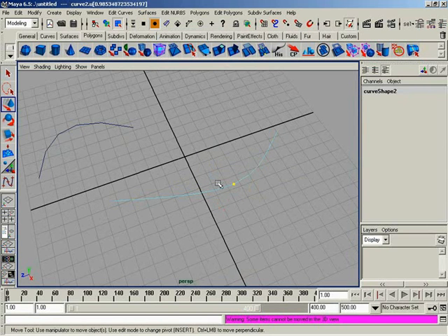And then let's just click to deselect all of the CVs. Now, curve points is yet another component. Not so much a component that you can go in and move around. It's really more of a marker, if you will. And this marker is extremely important in being able to tell a specific tool that I need an operation done right here. So I can come in here, I can click, I can drag, and then once I have my marker or a curve point wherever I'd like, then I can come up here to edit curves.